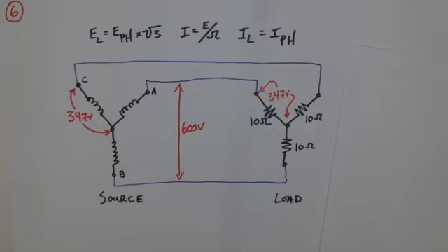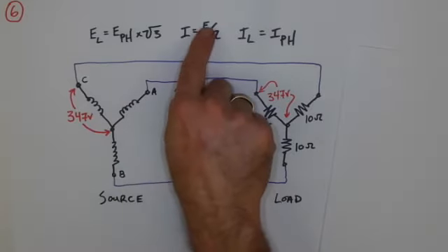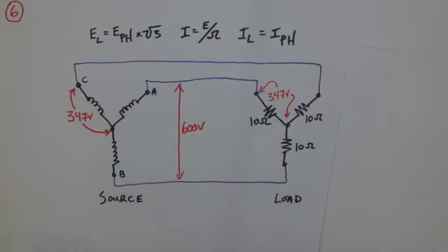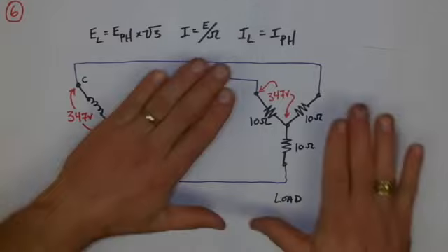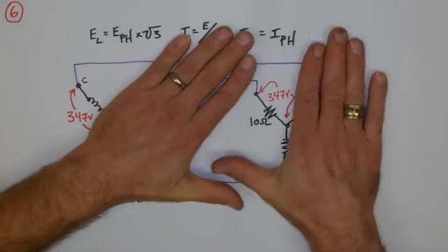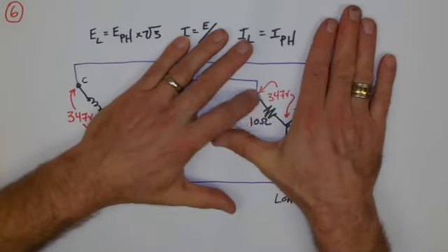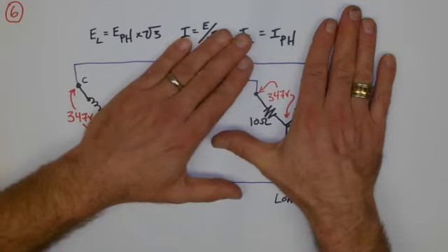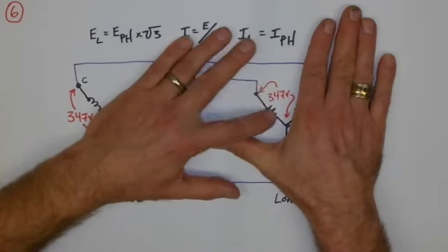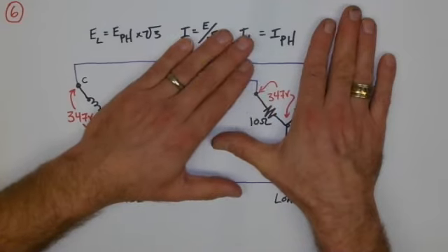That's simply Ohm's law. Current is equal to the voltage divided by the ohms. And people will often ask, well, is it going to be the line voltage we use or the phase voltage? And I say to you, if all we want to know is the current that's flowing through this section here of that resistor, then all we're using is the voltage available across that object, which of course is the phase voltage.